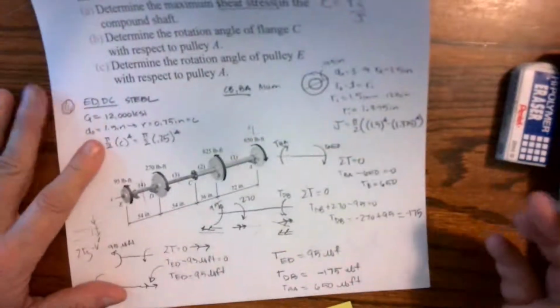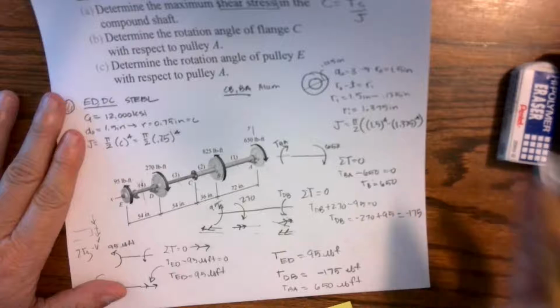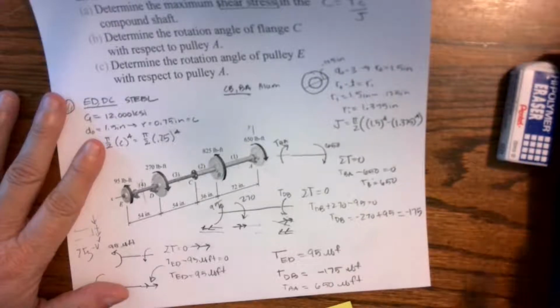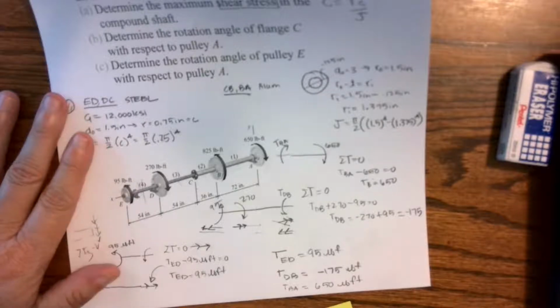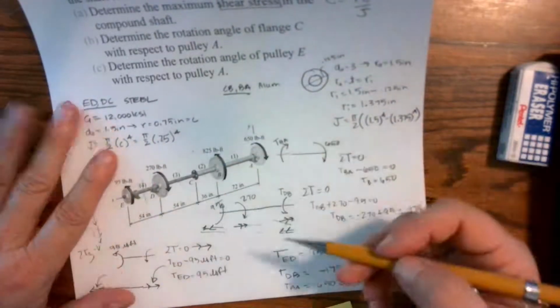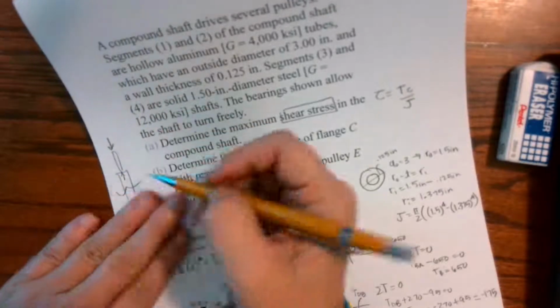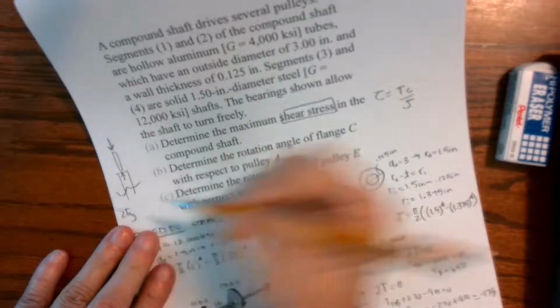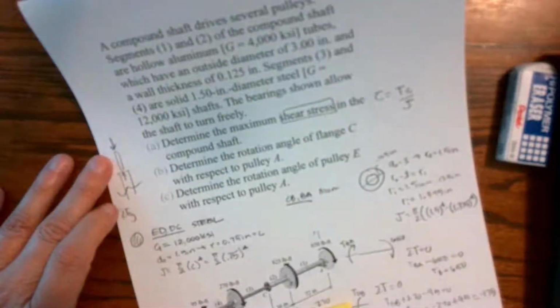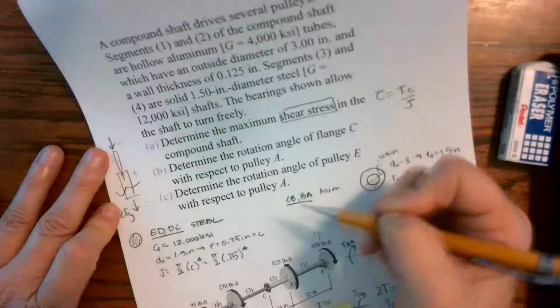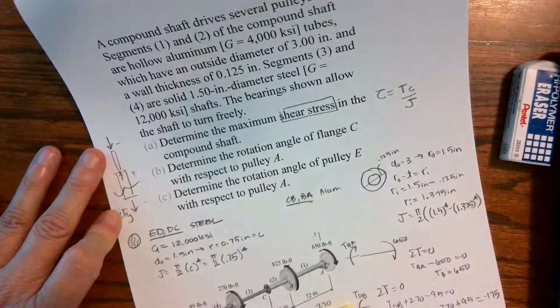This is like the wedding cake problems. If you are struggling at all with this, you've got to get some help. Okay, you've just got to get help. You have to know how to cut these things correctly and find internal. You cannot just look at the outside and just grab numbers. It's just like the wedding cake. Remember the wedding cake? If I have a force and I have a force and I cut here, I have to look at the whole thing and I have to sum my forces in the y direction, and I'm going to have a negative, plus, and then I assume this in tension, negative, and the math will tell me whether this internal is tension or compression.